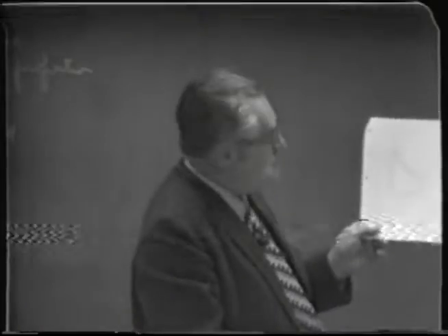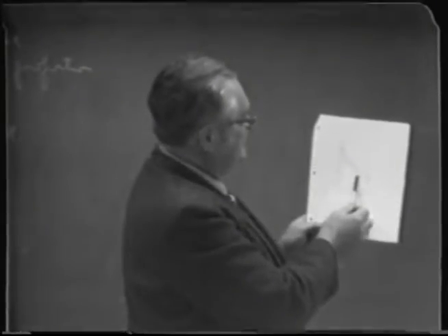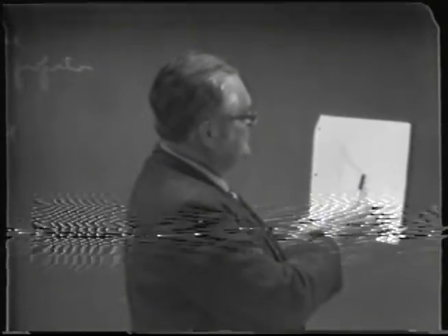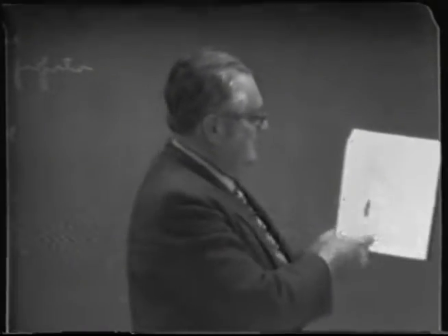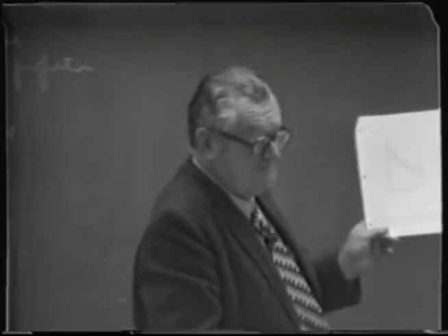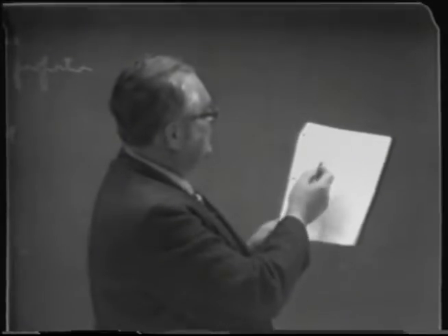So in the presence of ethyl alcohol, which would be the right-hand side of this chart, its volatility is higher, and so it's above the ethyl alcohol curve. But similarly, in dilute methyl alcohol and ethyl alcohol water mixtures, its volatility is less than ethyl alcohol. Something about 6.8 according to this chart here.